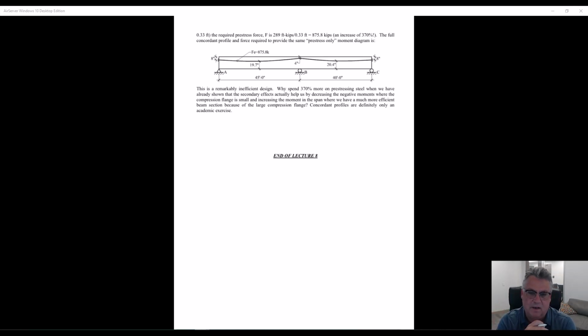So it will be the demand that changes, and that is very confusing to people who've never really understood what we're talking about. I've seen people try to match hand calculations with computer output, and they don't understand that the secondary moment needs to be included. They will calculate MU only and think that their program's giving them terrible answers on the amount of reinforcement that's required. That's just a lack of understanding, but it's not complicated. You'll be tested on it. Most students who study this will do just fine. And it's a very interesting, unique part of post-tension concrete.